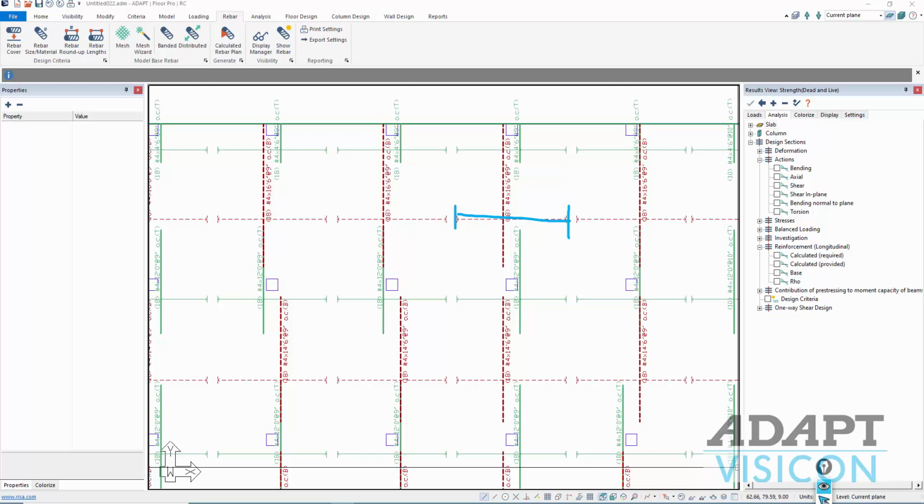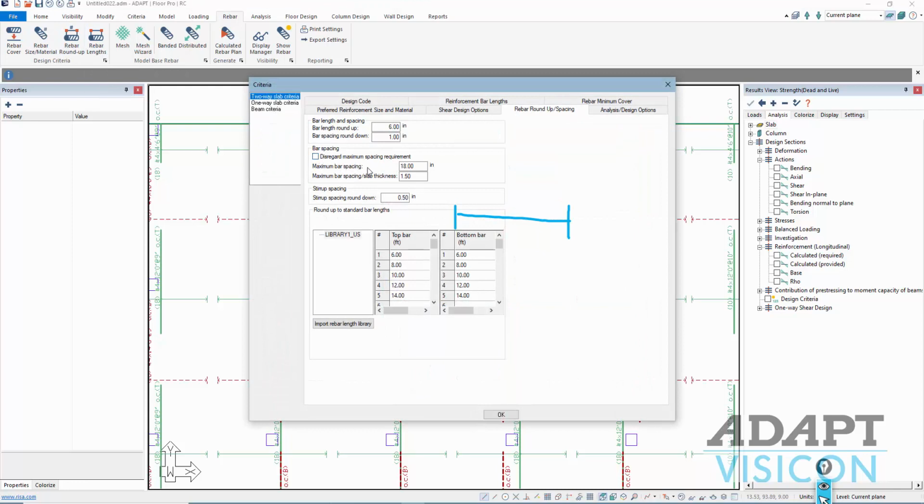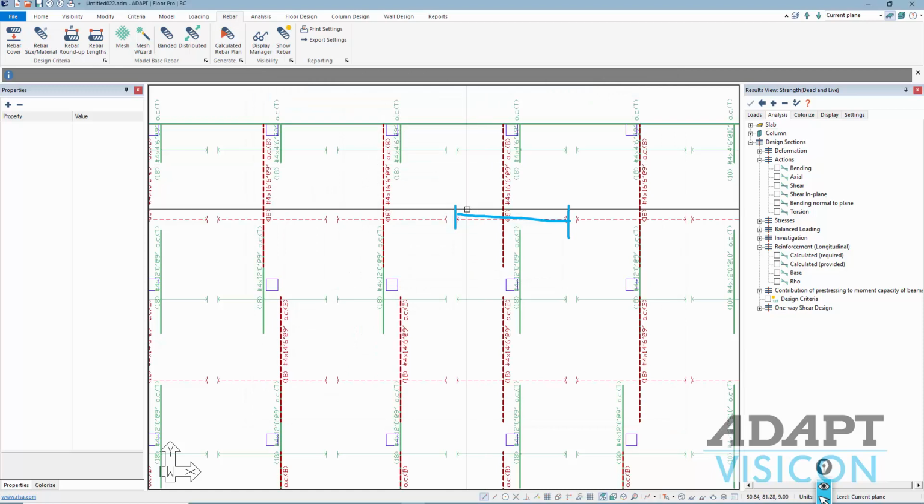There's an additional check made, which is shown here under Rebar Roundup, and this says if the spacing of those bars does not meet these two minimums, or maximums, the program is going to limit the spacing to this criteria. If the user wishes, they can turn that off, so really the outcome is whatever is calculated for strength or service. But this particular check may be affecting the total number of bars that is presented here on screen.